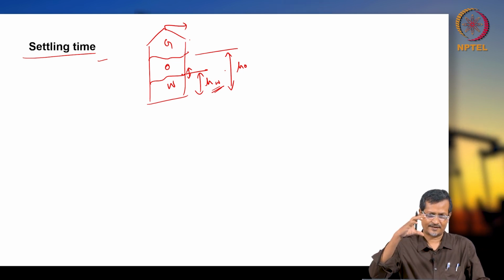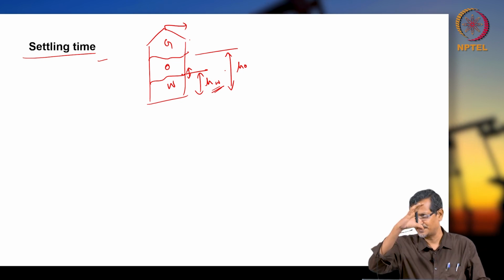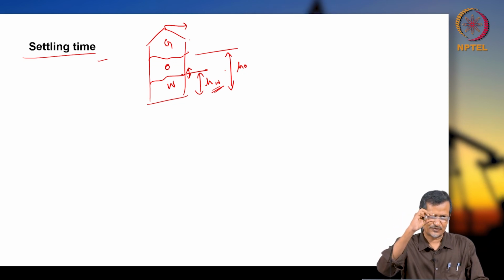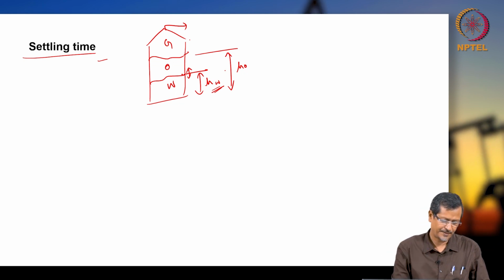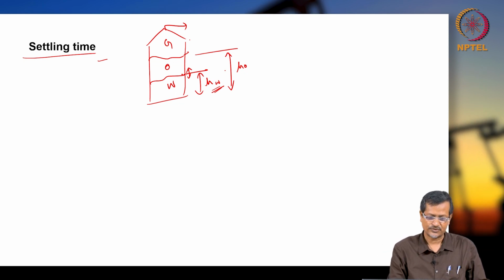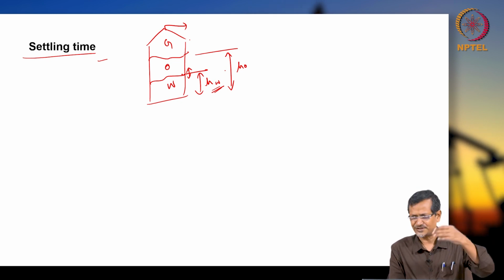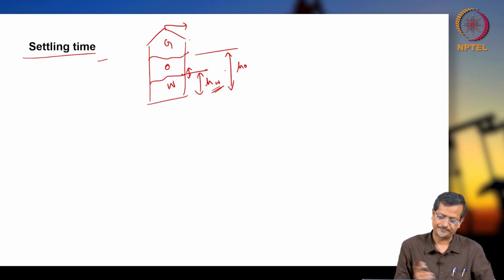Let us say total HW plus HO is fixed, okay. Now, water space you are giving more, so oil space is lower. So, when oil space is lower, that means oil will get less time, retention time is lower for oil, okay. But the opposite will also happen: if the total amount of oil is higher, then retention time is also higher, okay. Water time will be lower in that case, fine.